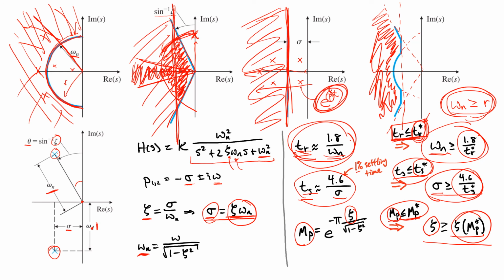And so it's very easy to tell once you put your root locus down whether or not your root locus will ever intersect in this feasible region, or if, for example, your root locus lives entirely over here and you never can reach these closed loop poles that will achieve your time domain specifications. And so this geometric interpretation is particularly nice to use in combination with our knowledge of the root locus, which is where we're going next.